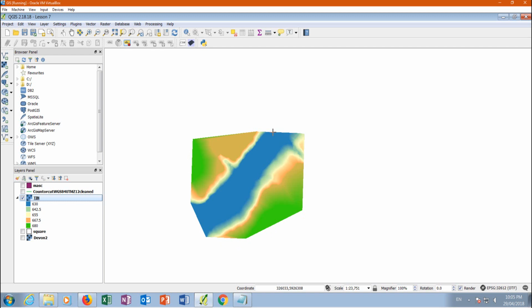Even, for example, if we have a contamination related with hydrocarbons, for example, a gasoline contamination, right? And you have a thin layer that is very permeable, where the hydraulic conductivity is really high because it's a layer of sand, and you have a lot of boreholes with this layer.